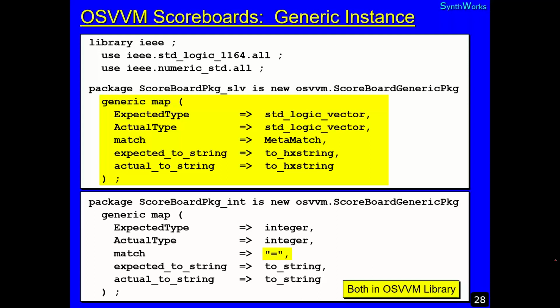And to_hstring, if you get a U, it prints it as an X. Okay, and it doesn't differentiate between 4 U's and mixed values. So to_hxstring does. If you get 4 of the same standard logic character in a row, it's going to print that. Okay, so except for H and L, it's going to print those as 0 and 1. Okay, and if it gets a mixture of things, it's going to print a question mark, and then in parentheses, it's also going to print a binary value to string.